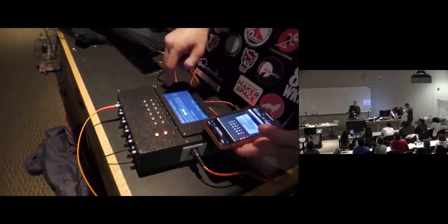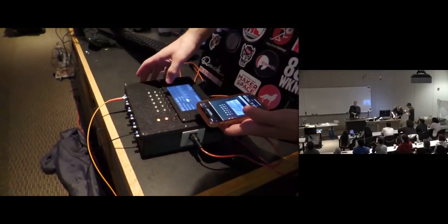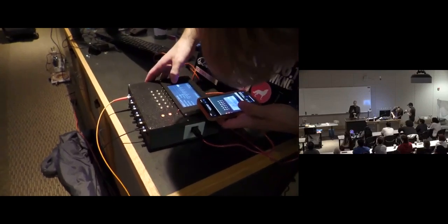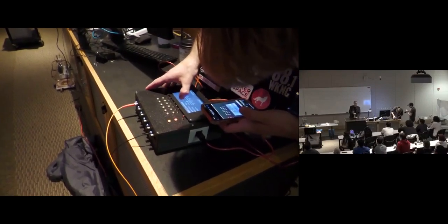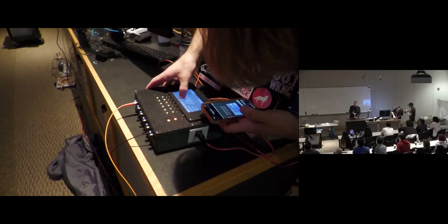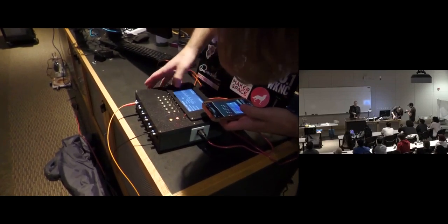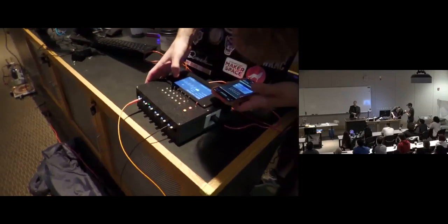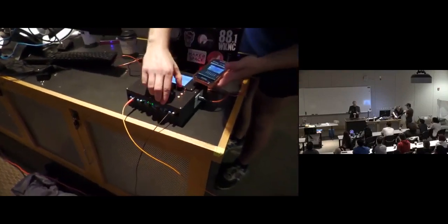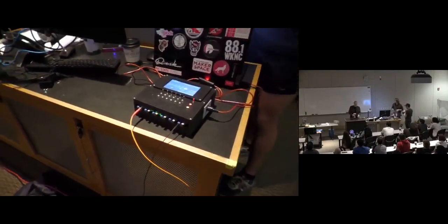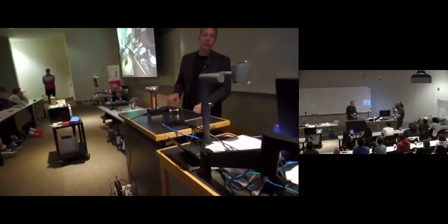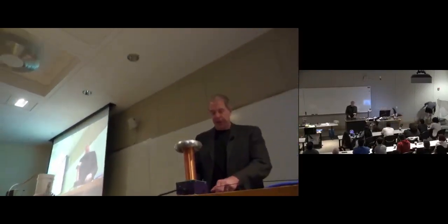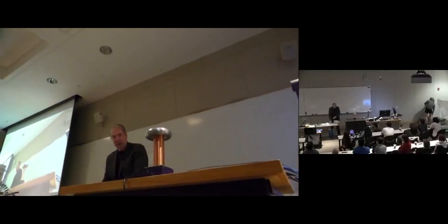And what he's doing is he's turning on the coil. He closes the switch, gets current to flow, and then lets it go once. And he does that maybe every millisecond. So that would give us a sound of a kilohertz. If he did it every 2 milliseconds, it would give us 500 hertz. So he can actually create the spark and make it sound different to us. So if we can make it sound different, Xander, can you do something more fun than just make a spark go in a range?